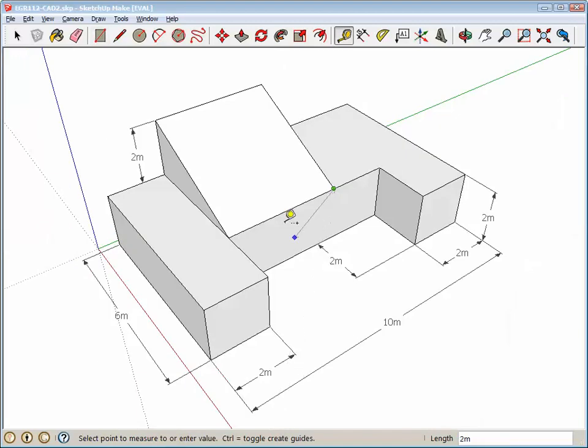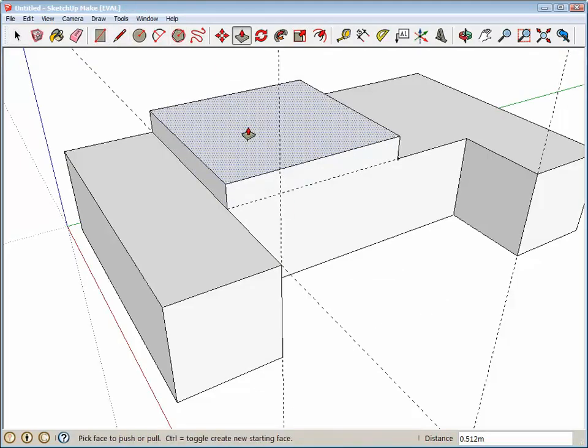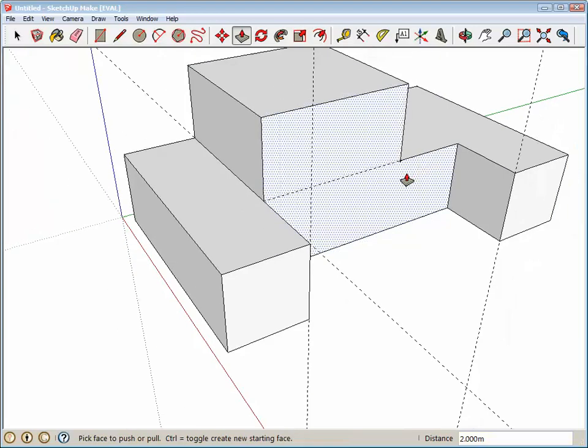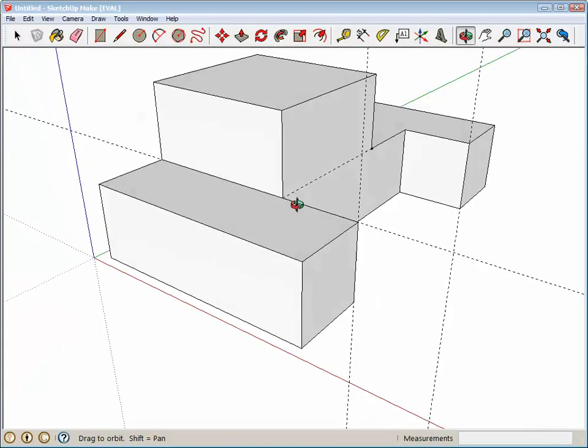Okay, and then you'll notice that it's 2 meters on the back side up there. So I think what I'm going to do is pull that rectangle up and then push this edge down to make it a wedge. So let's try that. Selecting push-pull tool, pull up a little bit, type in 2M for 2 meters, and maybe zoom back, orbit around a little bit. Looks pretty good.